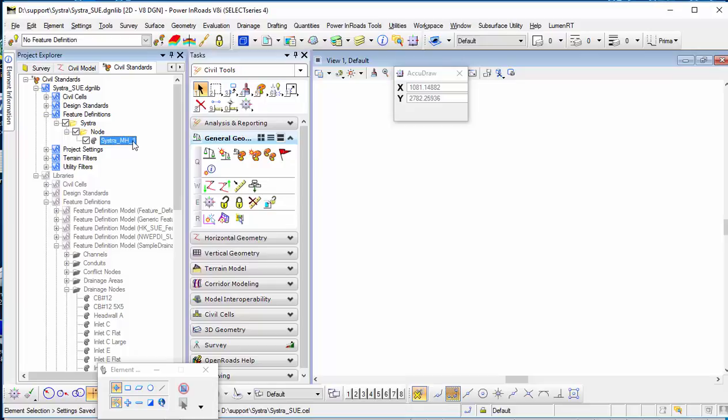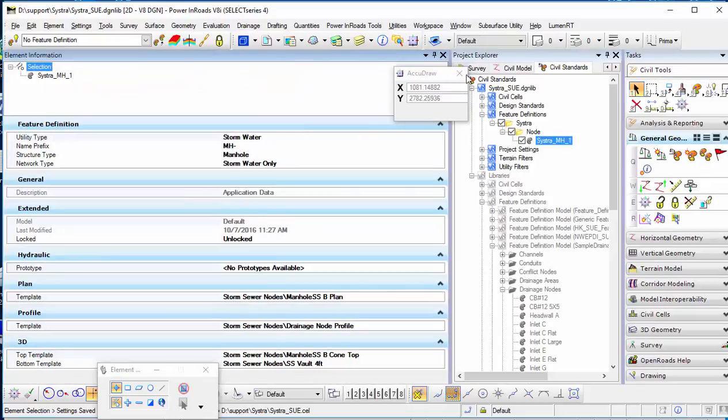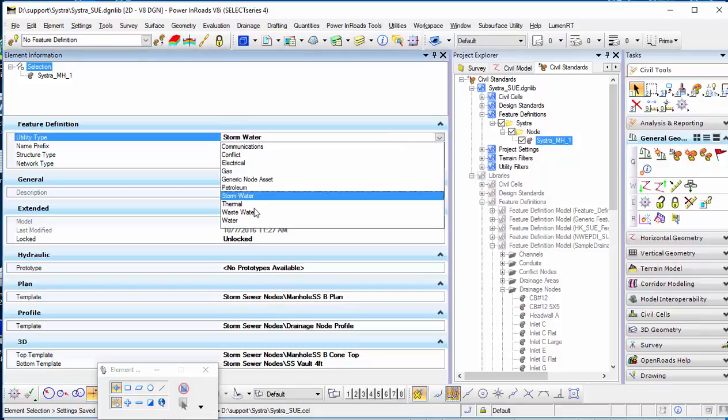Okay, after I copy this one here, I will click properties, and in the properties you will see I have some settings here. The first, which is very important, is you need to configure which of the element types here you need to use, because later you need to connect with different pipes. It also depends on which type of utilities you want to connect.